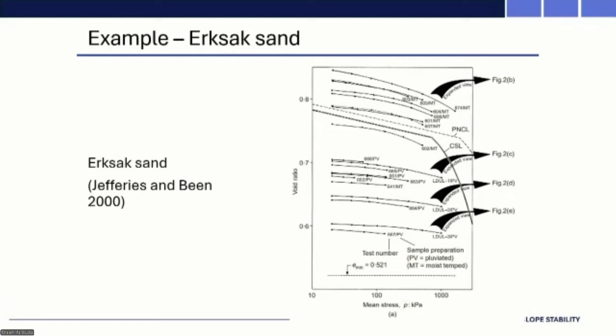And there's ways to determine almost the degree of transition. So if those normal consolidation lines converge at moderate effective stresses, that might be a different designation than if they converge at extremely high effective stresses. Sometimes those stresses might be equivalent to a 400 meter high TSF in terms of the stress required. So for a lot of tailings storage facilities, maybe 50 meters high and less, or even perhaps a bit higher than that, they're in that range where the convergence doesn't always happen.